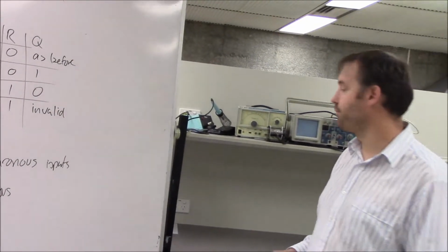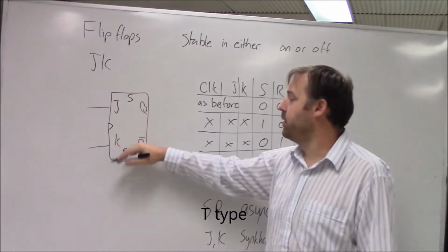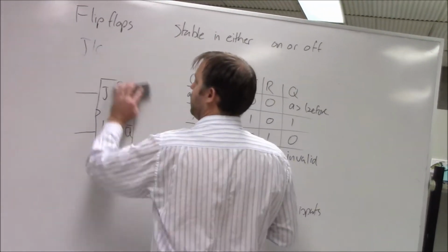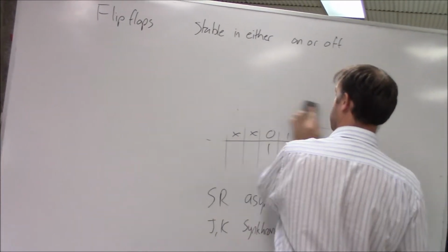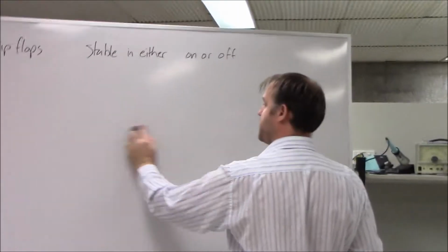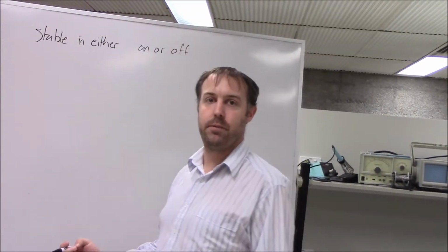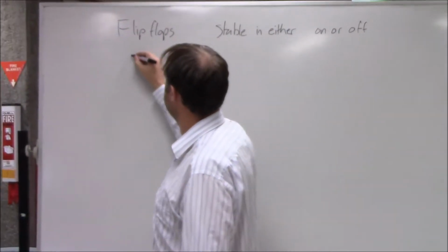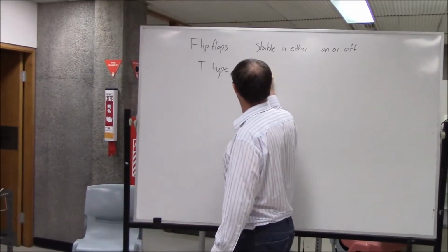Okay. So with the JK both being high, this sets this flip-flop to a toggle. So this is how we can make something called a toggle type or a T-type flip-flop. So they don't actually manufacture T-type flip-flops discretely, so you can't go out and buy a T-type flip-flop. You can buy a JK-type flip-flop and wire it to be a T-type. T-type, toggle.